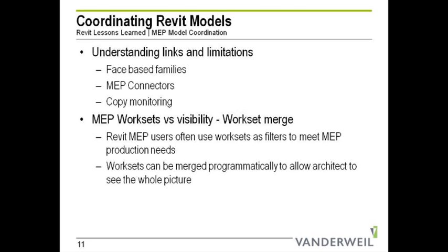Another thing to be aware of are MEP connectors. An MEP model cannot connect to your, for example, light fixture through a linked model. We cannot connect it to show it on our panel schedules, to show it on our schedules, to get the power flowing, same thing with the mechanical equipment. So if the architect chooses to lay out the light fixtures, what's happened in the past is that you basically have to copy all those and then paste them into your model or place one on top of each of theirs. And as you get updates, you have to move them around to make them work, because you're going to have them in your model to be able to link to them.